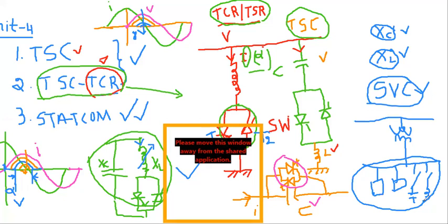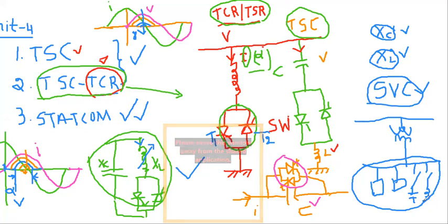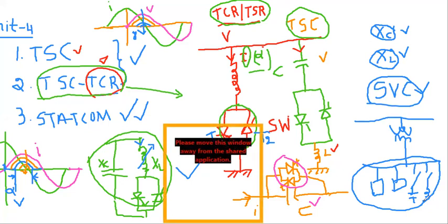But in the case of STATCOM, you have a storage, secondary storage will generally be there. Nowadays, STATCOMs are coming with renewable energy sources on one side, so that they have the capability to exchange real power also with the mains. That you get in the case of STATCOM, but that is completely absent in the static VAR compensator, SVC. Don't think that SVC is a different one. It is a combination of whatever devices we have discussed. That's all. So that is about the SVC.